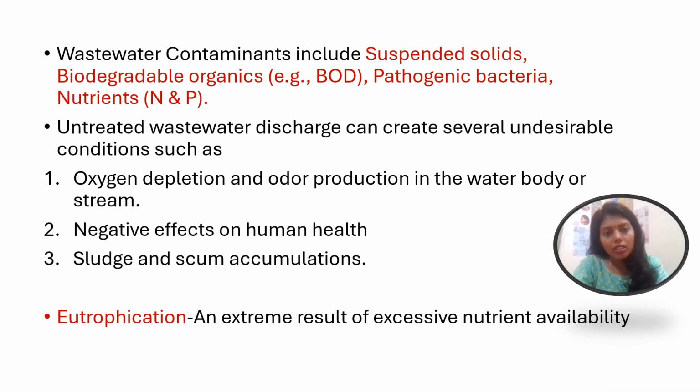And wastewater contaminants include suspended solids, biodegradable organics, for example BOD, pathogenic bacteria, and nutrients such as nitrogen and phosphorus. So the discharge of this untreated water can cause several undesirable conditions such as oxygen depletion and odor production in the water body, and it can cause negative effects on human health. Then sludge and scum accumulation. Scum is nothing but a layer of dirt.